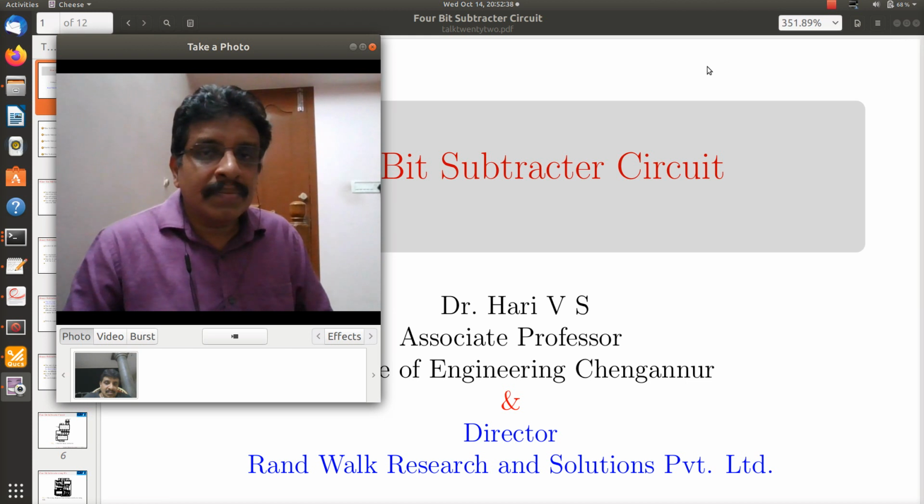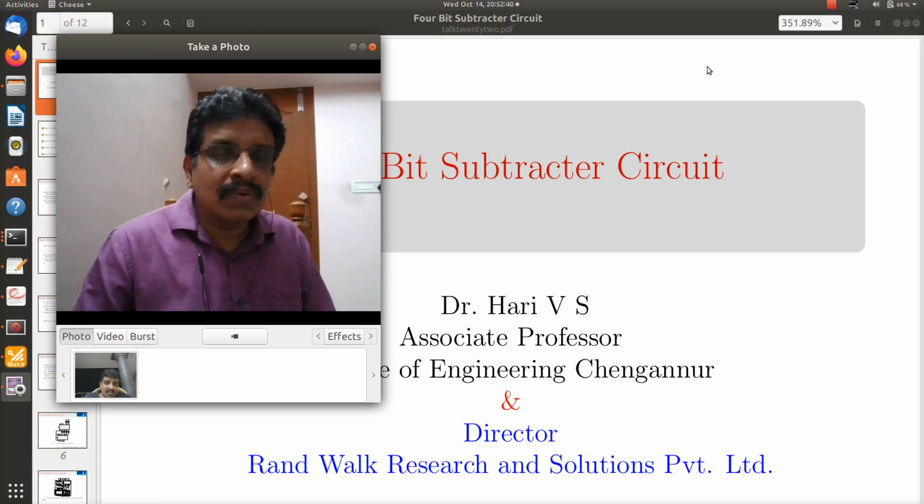Hi ladies and gentlemen, in the last video we have seen the full subtractor. Now these full subtractors are not the way we subtract numbers. Instead we use the 2's complementing method or 1's complementing method. So in this video I tell you about a 4-bit subtractor circuit with the 2's complementing method. It basically relies on 4-bit adders and a complementing circuit. So let me start with that presentation.